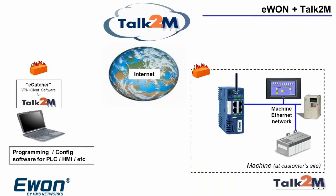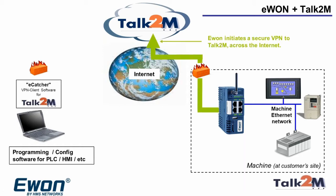So independent of what model you're using, you have the Ewon device and you install it in the panel of the control system that you send to site. And with the Ethernet ports on the front, you connect it up to the Ethernet network inside the panel. So connecting to the HMI, the PLC, the drives, or whatever else you have in your control system. The Ewon will have an IP address on that machine Ethernet network. What it then does is when you power it up and turn it on and it's configured, it makes an outbound connection out from the site to the Talk2M cloud.